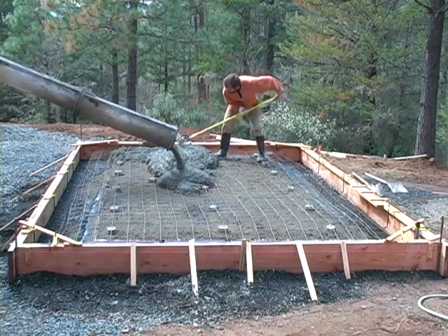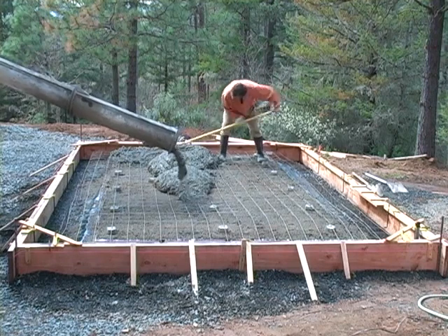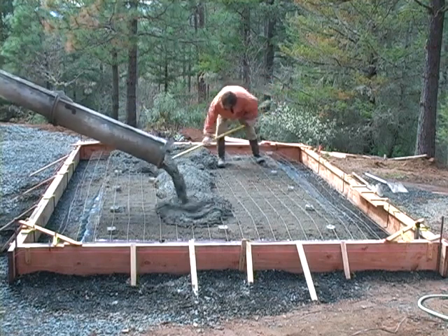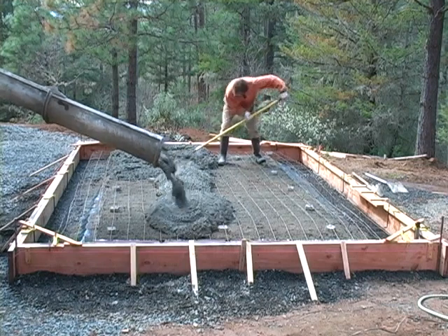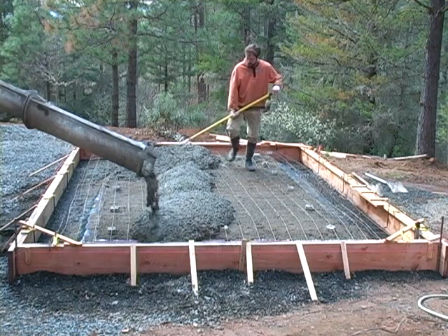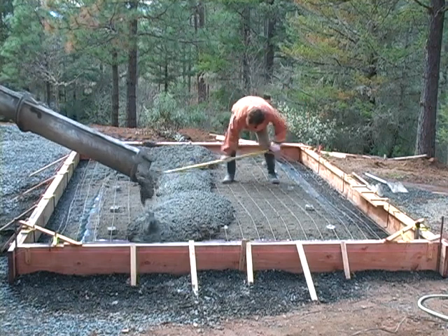The drier it is, the harder it is to move around the slab. So if you have the ability to keep it as a wet pour, it's a good idea to pour it as wet as the truck will allow you to do it, and then you'll have a lot of time to work with it, and you'll be able to move it around a lot more easily.